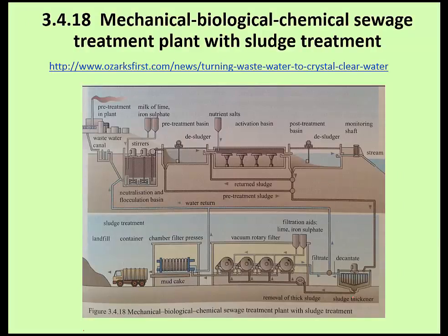And then in the last slide, he talks about combining all of these techniques. So what if you have a sewage treatment plant that combines mechanical, biological, and chemical sewage treatment? So putting it all in one block. He has a schematic here. Again, it's just all the parts that we've looked at put together, so you can see how they flow together from beginning material to the end deactivated sludge, and then the water, the effluent that's put back into the original source. So you can see how they tie together.